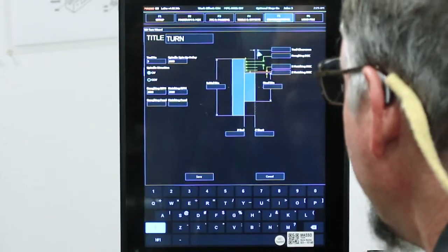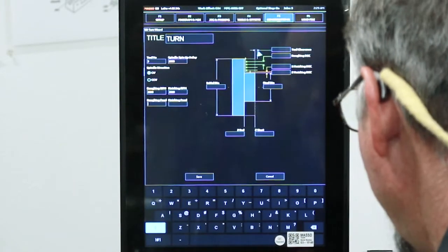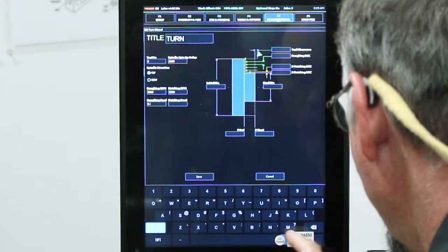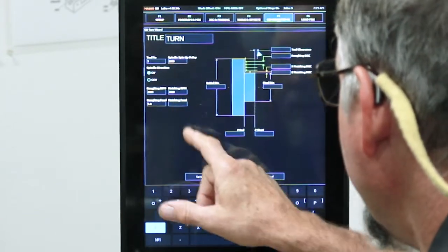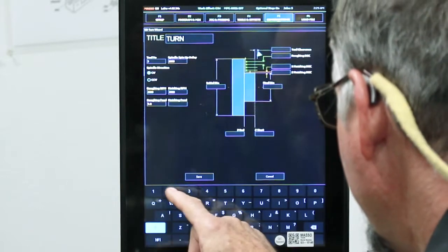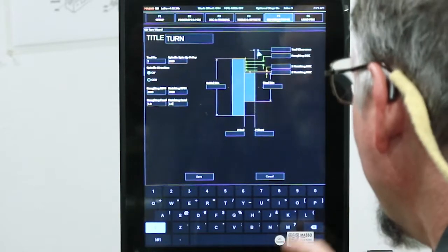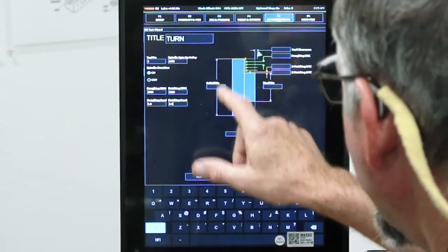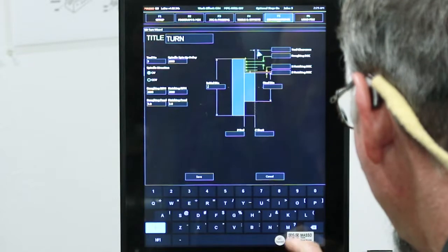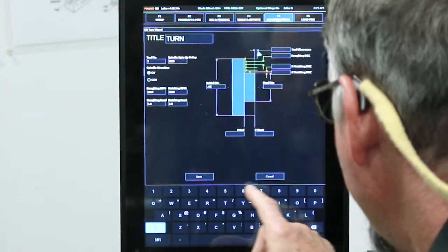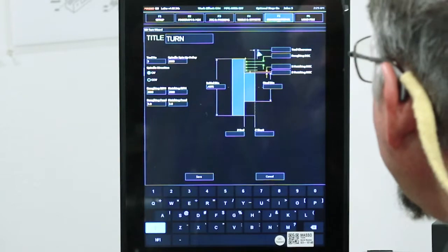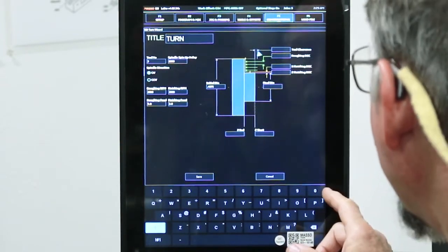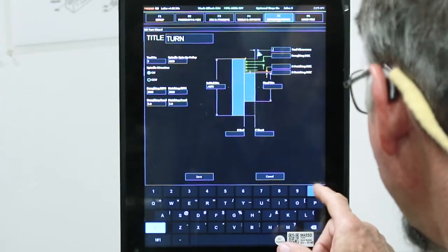I'm just doing a skim cut. Roughing feed rate, this is inches per minute. We'll go 5.0. Finish feed rate, 2.0. Okay, so the initial diameter of our stock is 7/16, so 0.4375. Tool clearance on the face, I'll say 50 thousandths, 0.05.